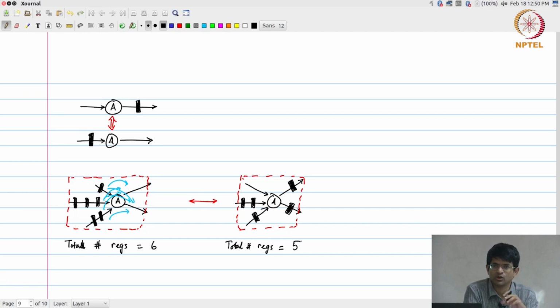Where are you able to place the registers, in which part of the circuit do the registers go, and how are you able to use them. So, it is possible to set up different kinds of optimization problems depending on the cost condition that you want to optimize for. The retiming by itself is just the basic transformation, the concept that allows you to do this movement of registers that you can then use systematically.